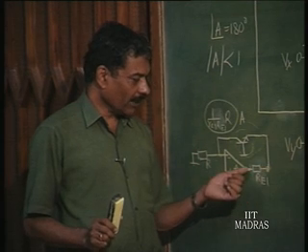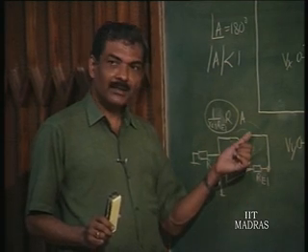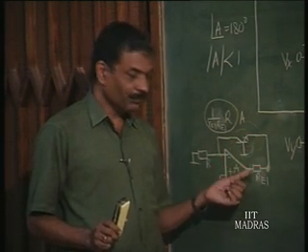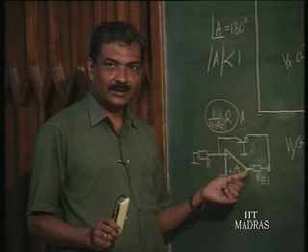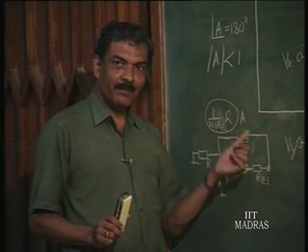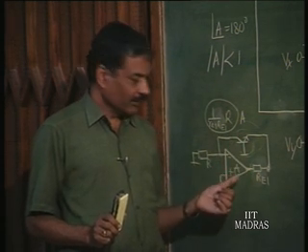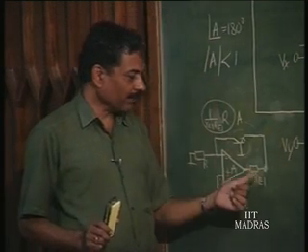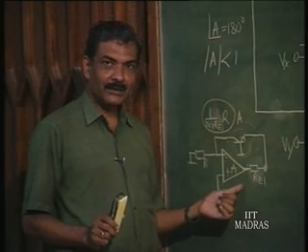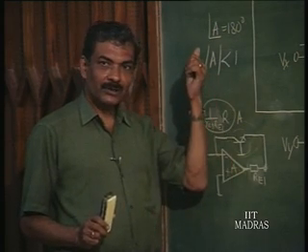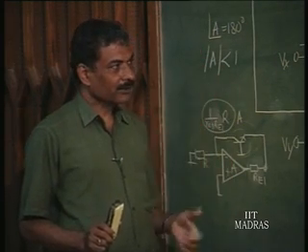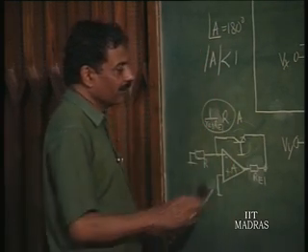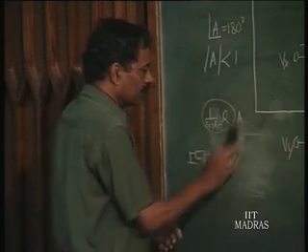Normally, if you have not put a resistance here, the voltage would have been the diode voltage, but now that you have put a resistance, this voltage has to rise up to 1 milliampere into Re1. That should not go up to the supply voltage. That means Re1 cannot be increased so much that it goes up to supply voltage. So, this is the limitation of this circuit.